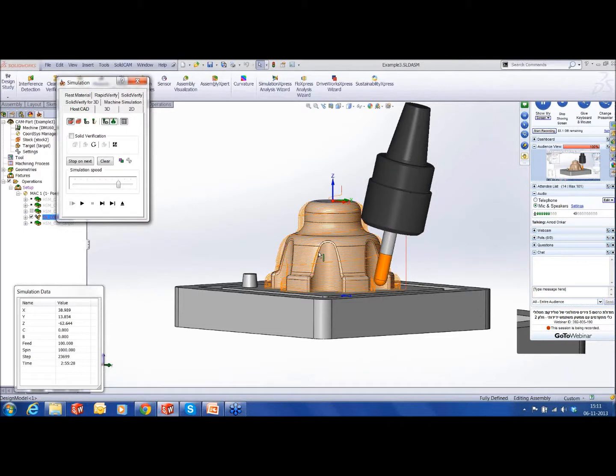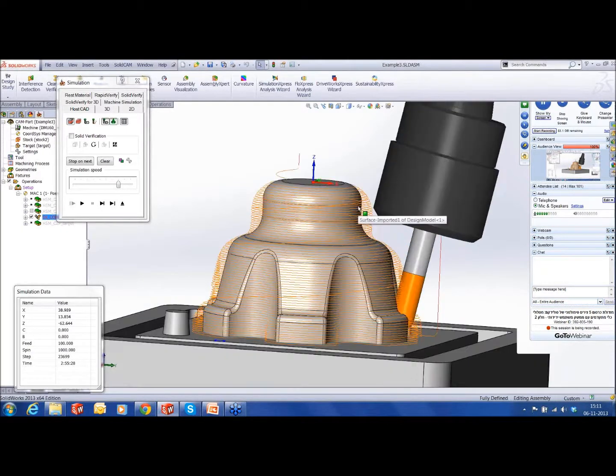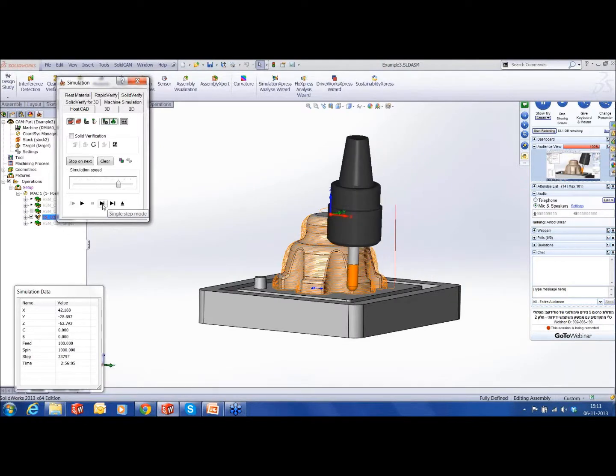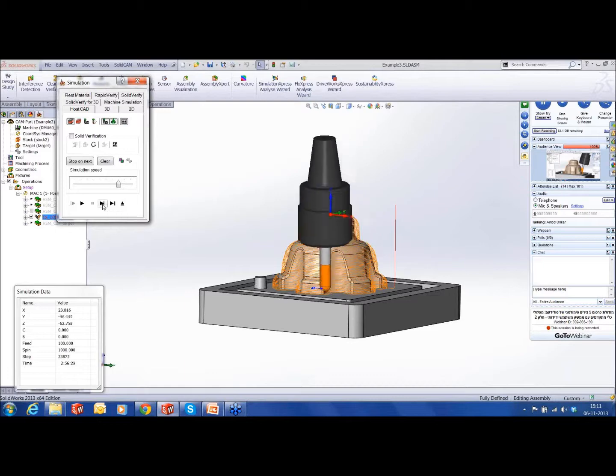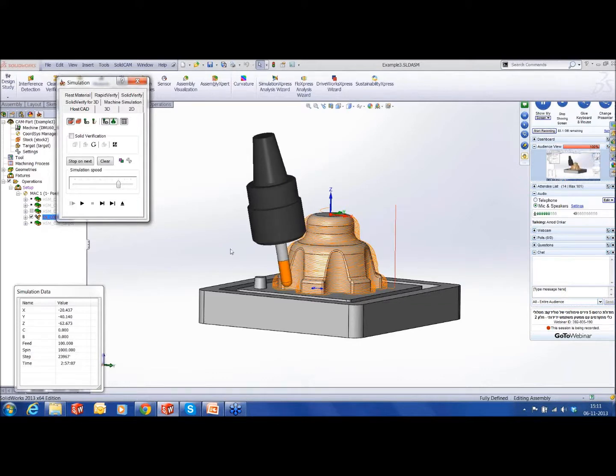Again, when it's going inside, since the holder is going to come very close to the cut area, it tilts the tool. So with this, I can actually use a 3-axis tool path, convert it easily and smoothly to 5-axis. And thereby I can use shorter tools, get much better surface finish, much better cutting parameters.